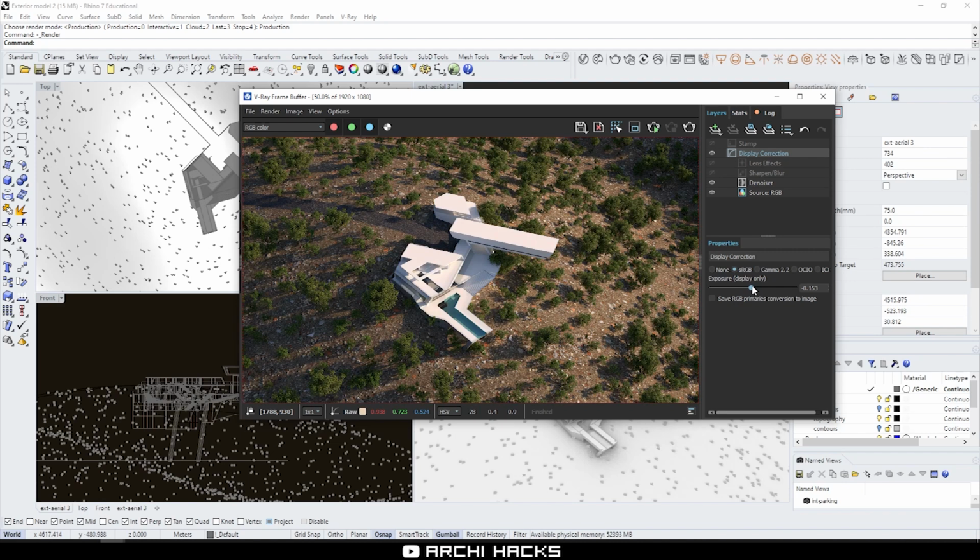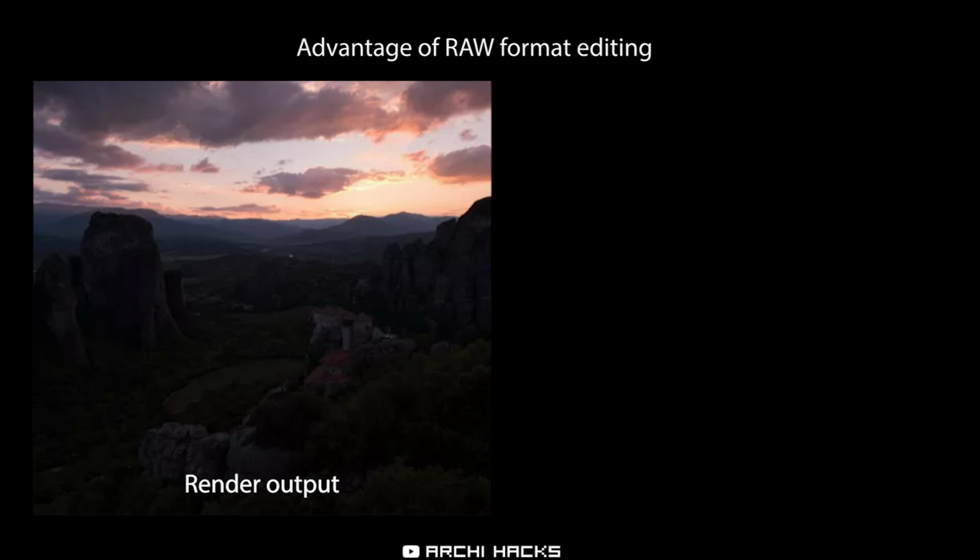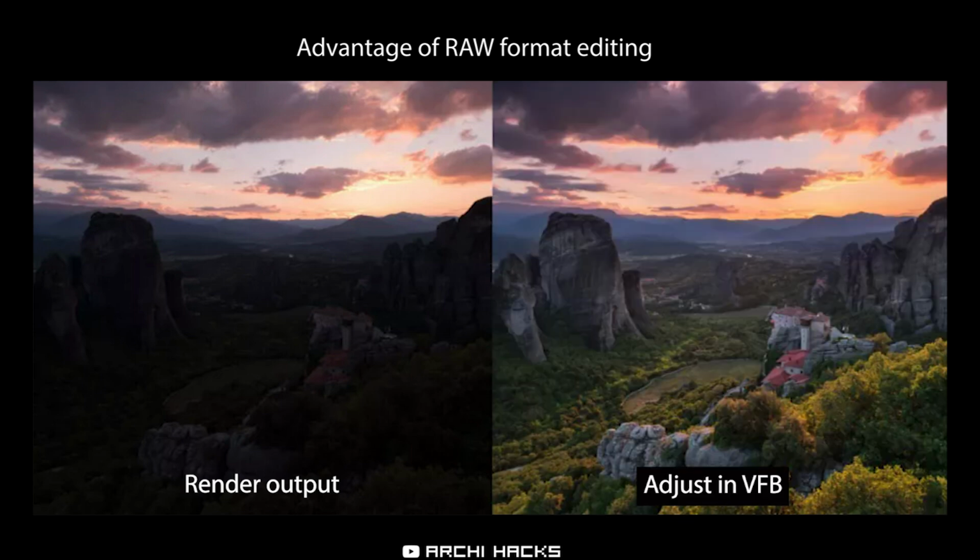Well, the difference is that once you export these images, they become flat JPEG images. However, when you're editing in the VFB editor like this, the image is still in its raw format. And raw means there's a lot of information, for example, in the shadows that is not visible right now, but it becomes more visible when you increase the exposure in the VFB. However, had you exported this image into JPEG format, that would have been lost.